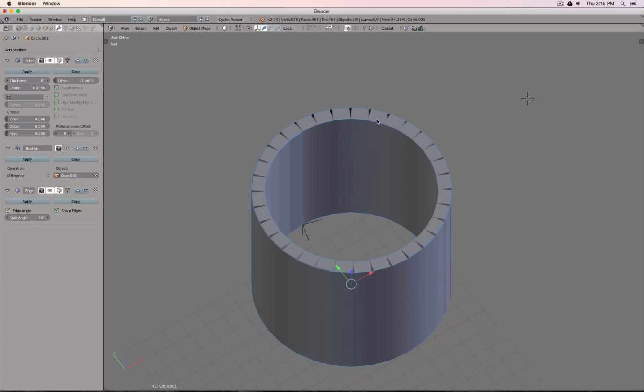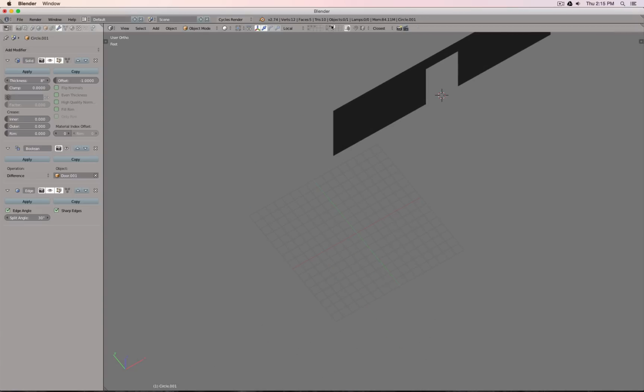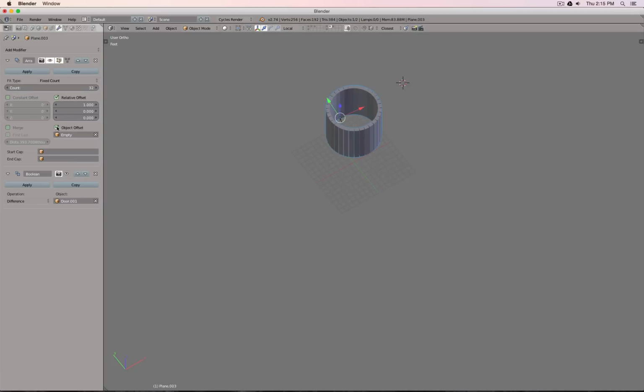The other reason why this approach with those triangles outside works better, in my opinion, is that if you want to make an oval, etc., this is going to be very, very easy. So you first need, of course, to figure out how long this piece has to be so that we can roll it into a circle with the correct dimension or diameter. And then, well, all the cuts, folding it.